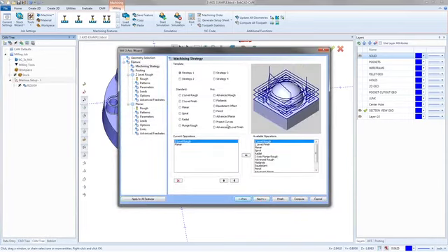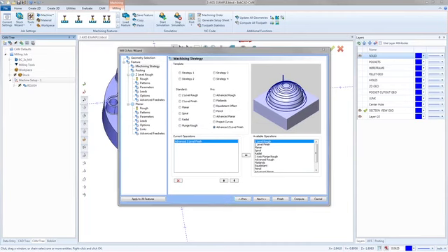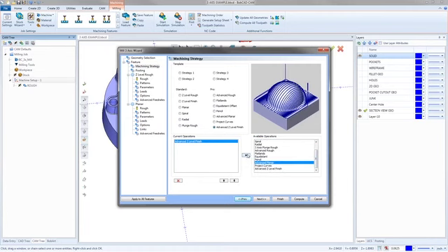All right, so for the machining strategy on this one, I want to do a finish pass that's really good for the walls, which is going to be the advanced Z level. So I'm going to start with that one. But I know for a fact with this advanced toolpath or any of these Z-level toolpaths, they hate cutting flatter floors. You could even see it in this picture right here. As it gets to the top, this big gap is still going to be an area that doesn't get cut. So I want to make sure that I have the proper toolpaths in place. So I'm going to start with the advanced Z-level finish, and then I'm going to come in with the advanced planar after that. So we got the 2 of them.